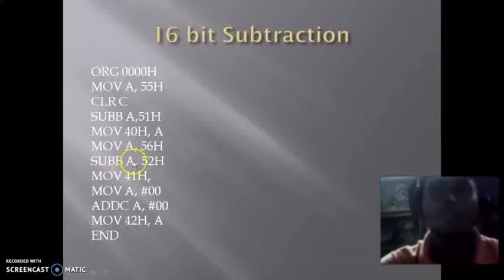Now the data in A will be stored into 41H, and similarly we will check whether borrow is generated or not. So that's why 00 will be stored into the accumulator, and next we will use the ADDC instruction, so that we will check whether borrow is generated or not. If carry is generated, if carry is set as 1, then we will get the result as 1, otherwise that will be equal to 0, and the result will be stored into 42H. So that is the end of the subtraction program.